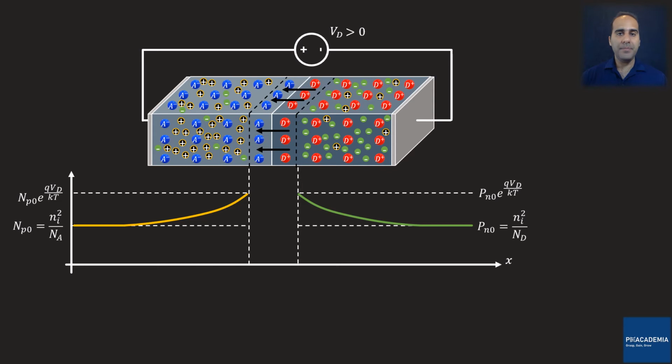Now, think about it. The P semiconductor has lots of holes. Holes here are the majority charge carriers. Under the forward bias, the P semiconductor is hosting electrons injected from the N semiconductor. These electrons recombine with the holes in the P semiconductor, and guess what happens? Photons are generated. On the other side of the semiconductor, the same scenario takes place. The holes injected from the P semiconductor recombine with the electrons in the N semiconductor, and this produces photons.